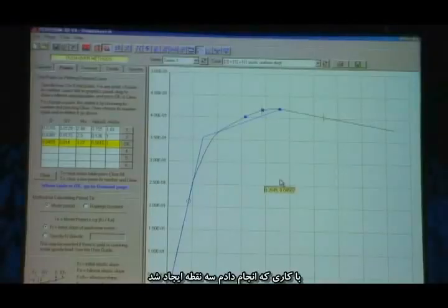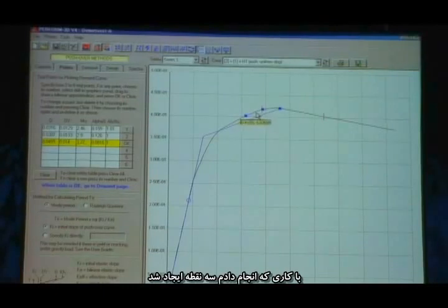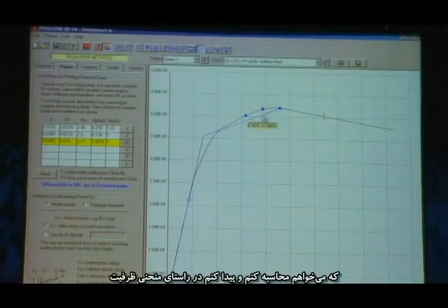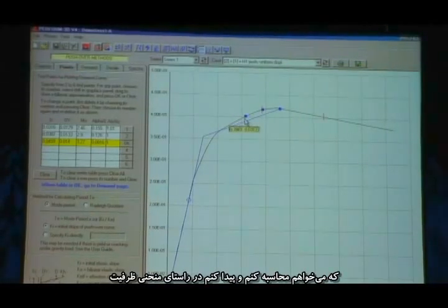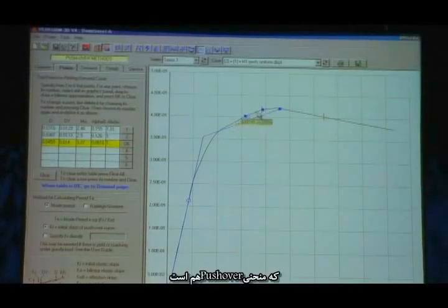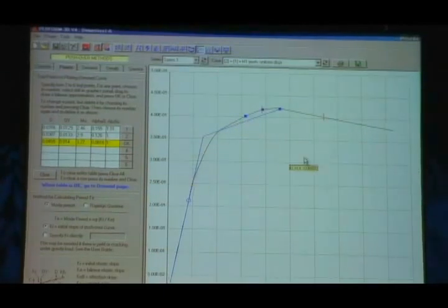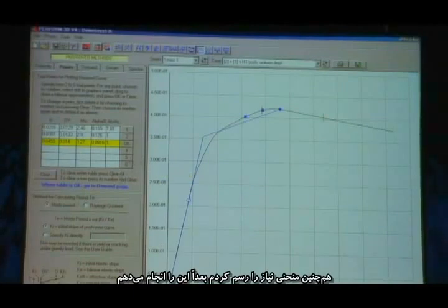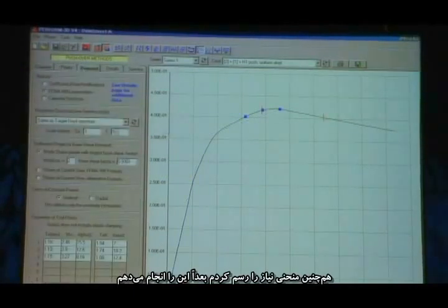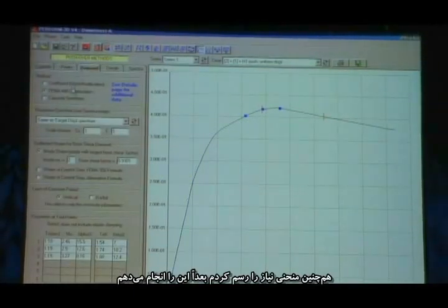And what I've done is generate here 3 trial points. And I'm going to find out that this is along the capacity curve, which is the pushover curve. I'm also going to plot a demand curve. And let me do that next. There are a number of different pushover methods. I can't go into the differences here.